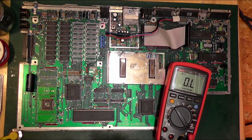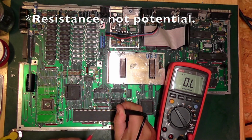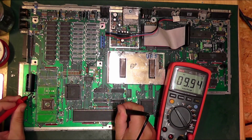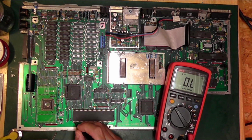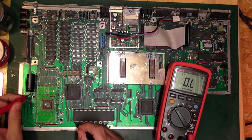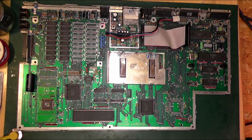Now on these boards, they are normally 10 kilo ohms. So if I were to measure the potential there between that D5 pin and our positive 5 rail. There we go, 9.94 kilo-ohms. So it's a 10k resistor. Now down here I believe this is the address line 4 pin, I think. Is that address line 4? Address line 5. Okay, so it's data 4 there and address 5 down here. And if we measure the same thing, 10 kilo-ohms. Now that's fairly standard, to be honest, for these old machines, but